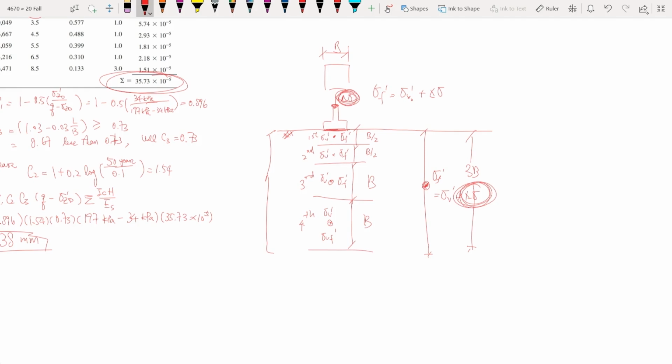So we have different methods we talked about in 366 using the DM values, DM 7.1 like a menu, and there are some design charts to find out the factors for how the stress changes with the depth. So that's why we need to divide this into different layers, such that we better capture the change of the stress from the foundation.